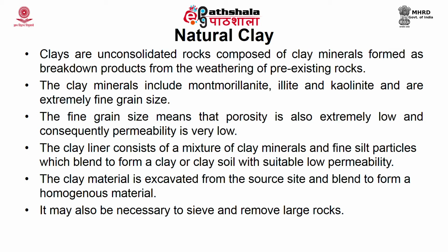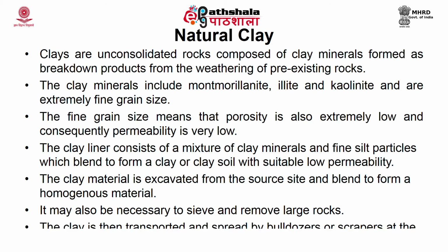So, it is always necessary that you sieve the clay and remove the large rock particles. The clay is then transported and spread by a bulldozer or a scraper at the site. This is how natural clay is used as a liner material.